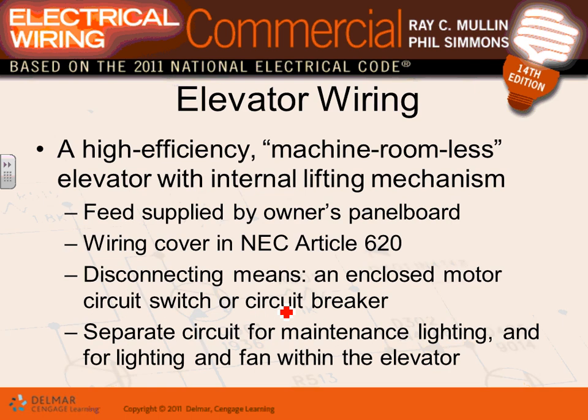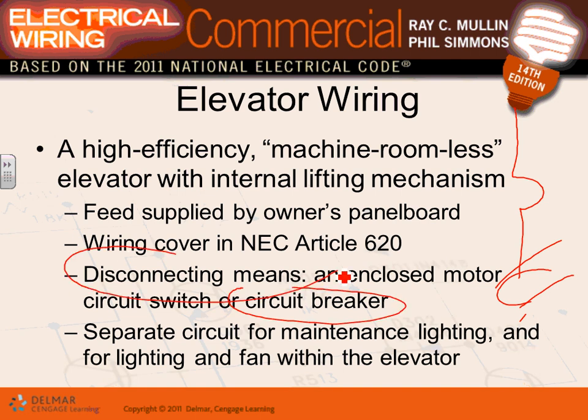All right. So elevator, we have a circuit that feeds the elevator, guys. The elevator does not have a machine room. Machine roomless elevator. Lifting mechanism, feeder supply. You have a circuit that feeds the elevator. The elevator, guys, is a pump, so you size it exactly like a motor. It needs a disconnect, typically a circuit breaker or a fuse disconnect, right next to the elevator. And also for maintenance, Adam, inside the elevator, you need light and fan.